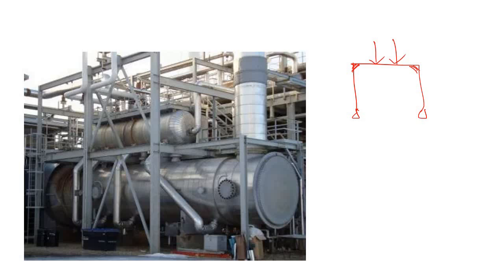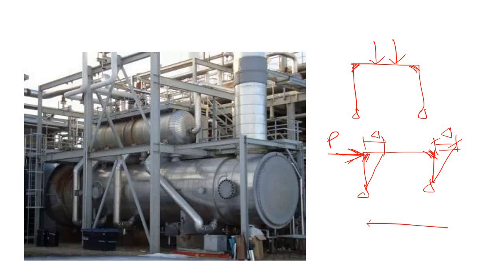Okay, and also if you have a lateral load, in that case you can also use a moment connection to make this frame stable. But the problem is, in the case of a moment connection, due to this lateral load there is a huge lateral deflection. So due to this huge lateral deflection, you need to provide some bracing, because the lateral rigidity of a braced frame is much higher.